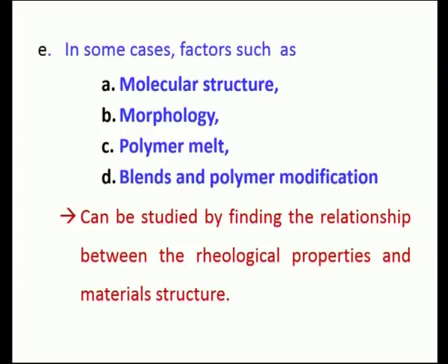In the molecular structure, how well the molecules are distributed, like narrow molecular weight distribution or a wide molecular weight distribution. The morphology here refers to whether the polymeric material is an amorphous material or a crystalline material, and for polymer melt, generally the crystalline materials have a very high melt temperature.